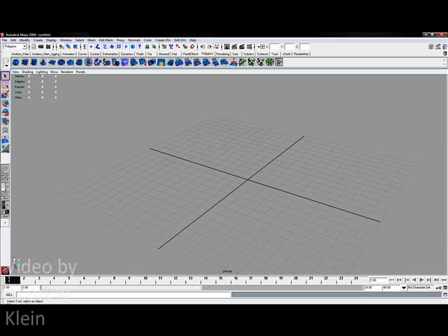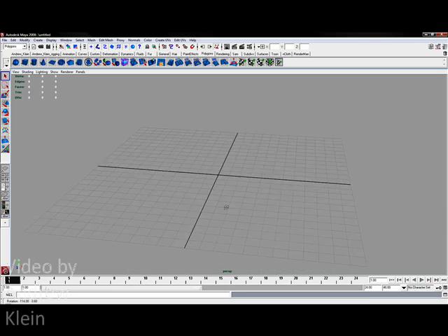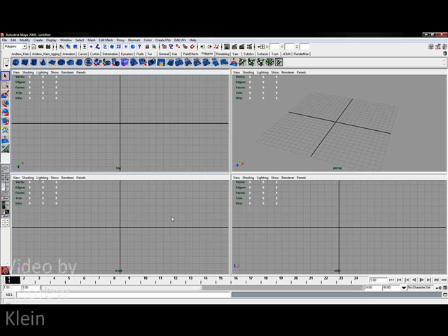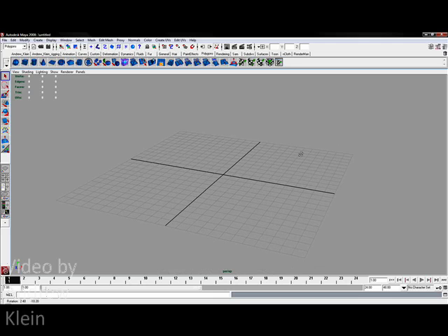Now, one of the things you will notice is that down in the lower left corner, there's going to be a gizmo which tells me my X, Y, and Z directions, which axis is facing forward, to the left and the right and to the sides. Now, when you're building, you're going to want your Z-axis to face forward, your X-axis to face towards the right, and your Y-axis to point up and down. This is because these axes are actually going to correspond to the top, front, and side views in your orthographic cameras. I hit spacebar to return to my perspective camera.